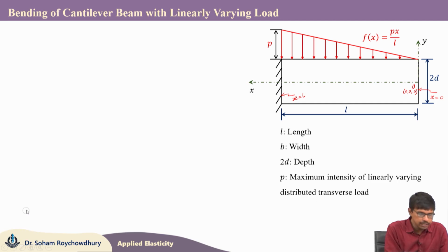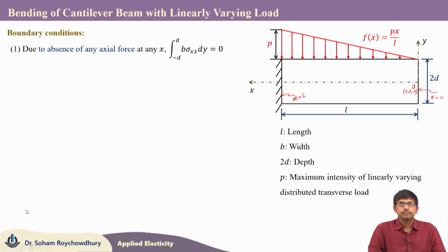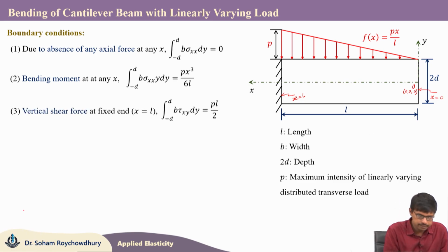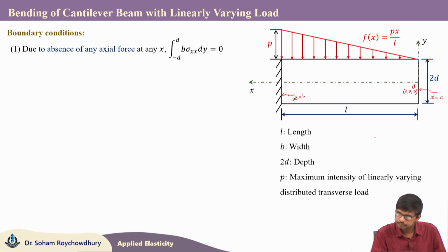Now, coming to the boundary conditions. As there is no axial force present in the problem, we have integral b sigma xx dy equals to 0, integral from minus d to plus d. Note that total depth is 2d. So, the range of y is from minus d to plus d, not minus d by 2 to plus d by 2. Total depth is 2d here and x is varying between 0 to L.